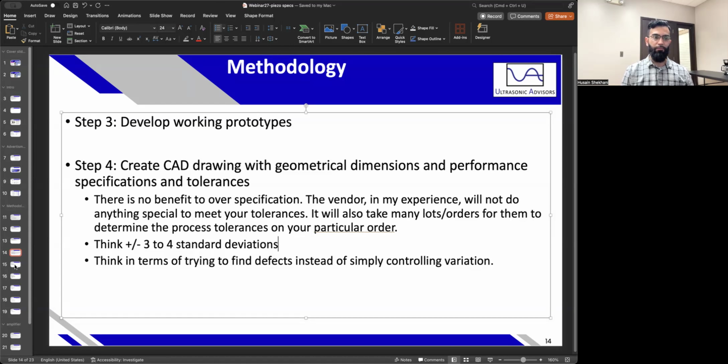So even if you just specified capacitance, it may actually just be sufficient, because based off of the whole process, if you just specify capacitance, they're not just going to send you a capacitor with that value. If they actually still make the process the same, all those parameters track. Like D33 will track with capacitance, and that almost might be sufficient. But we can still add more parameters legitimately, so we do. But realize that one parameter usually scales with other ones.